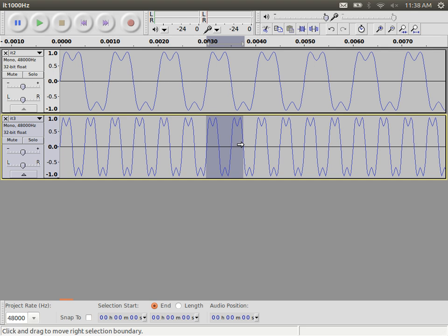for signal A, we can transmit 2 bits. In the same time with signal B, we could transmit 4 bits. So in this period, high, low, here, high, low, high, low. Oh, sorry, I've missed a part. And compare the characteristics. Signal A, data rate 2,000 bits per second. Signal B, data rate 4,000 bits per second. Frequency 1,000, frequency 2,000, bandwidth 2,000, bandwidth 4,000.